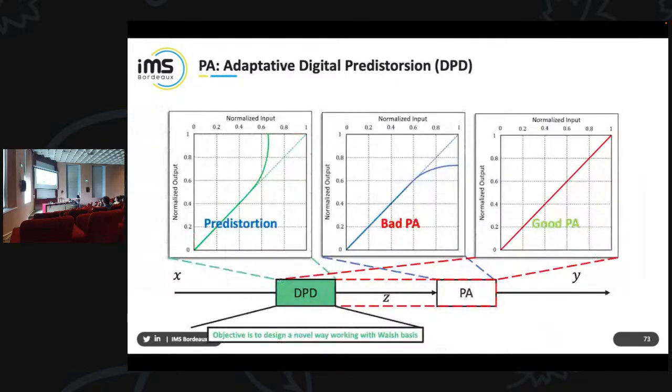A linearization is pretty easy to understand. Your PA, power amplifier, you can see here, it's like a logarithm in its characteristics. And if you want to compensate a logarithm, what do you put in it? An exponential. Logarithm of an exponential is just, sorry, I don't know the word in English, but this is what we have here. We have compensated completely the behavior of the PA, which is not linear, by creating what we call a pre-distortion. You pre-compensate it.